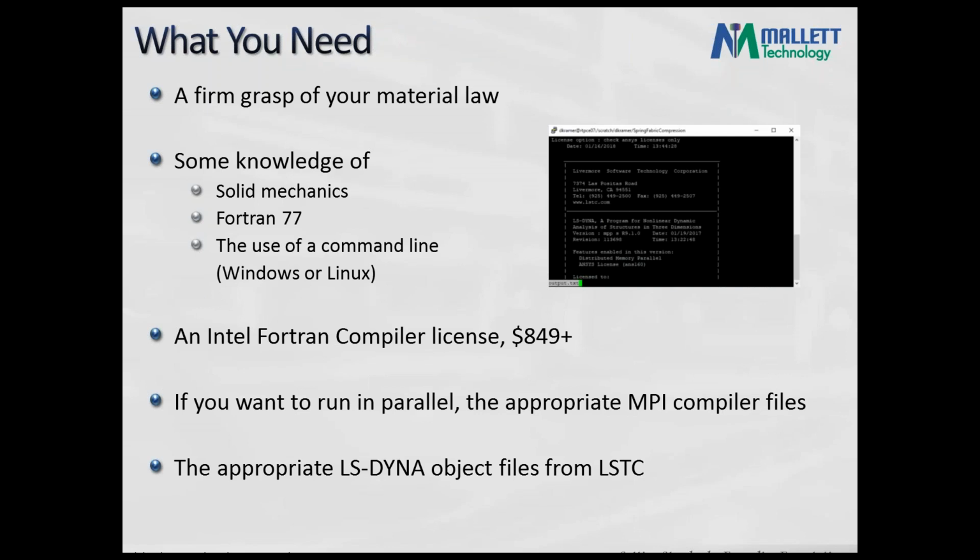Before you get started, what you really need is to know the material law that you want to implement inside and out. You need to know some solid mechanics. You might have to go back and refresh yourself. I know I did when I had to make a custom material recently. You need to know some Fortran, and you need to be comfortable using the command line, either in Windows or Linux, whichever one you intend to run LS-Dyna in. And unfortunately, you're going to need an Intel Fortran compiler license, which is about $850.